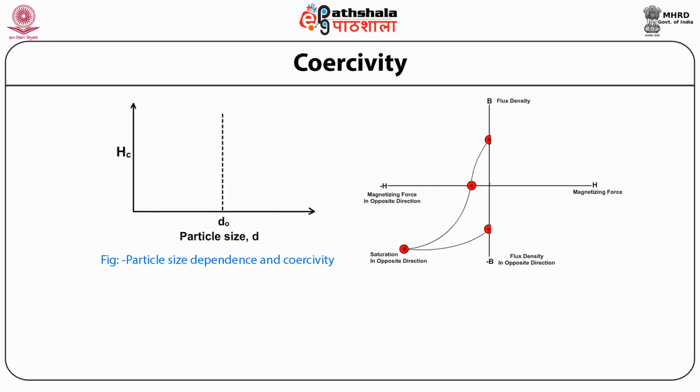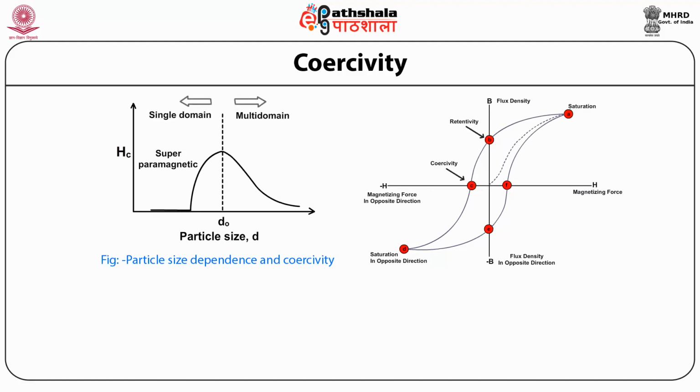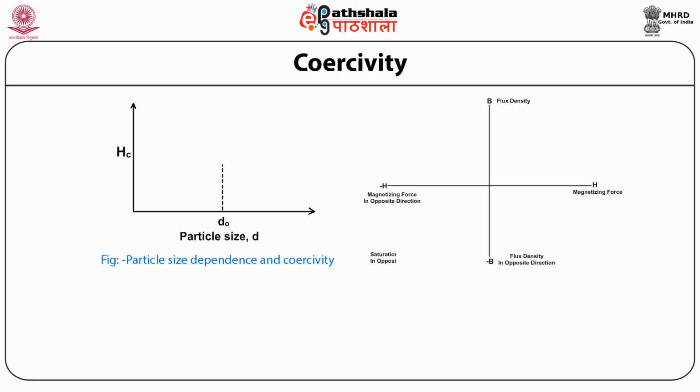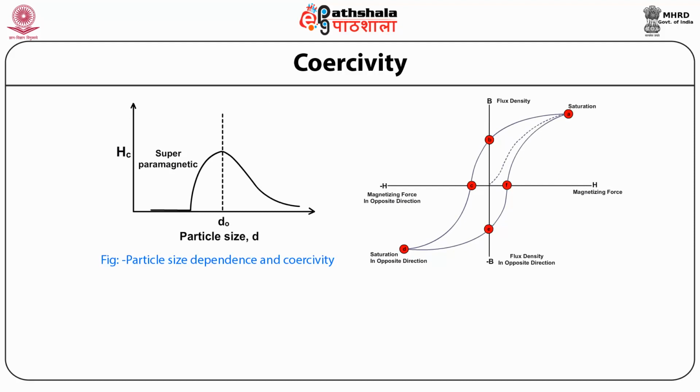This coercivity measures the resistance of a ferromagnetic material to becoming demagnetized. Coercivity is usually measured in oersted or ampere per meter units and is denoted Hc. It can be measured using a BH analyzer or magnetometer.